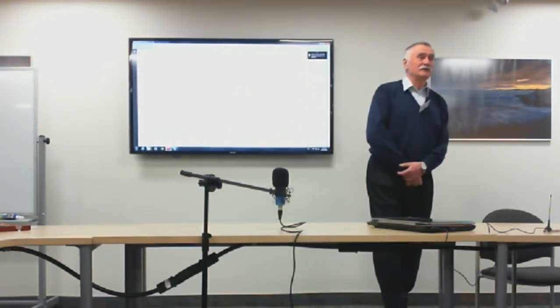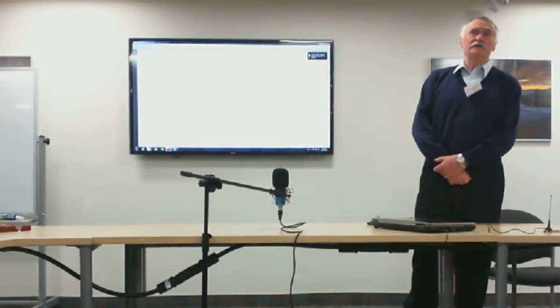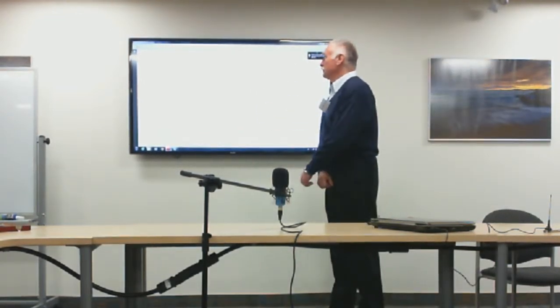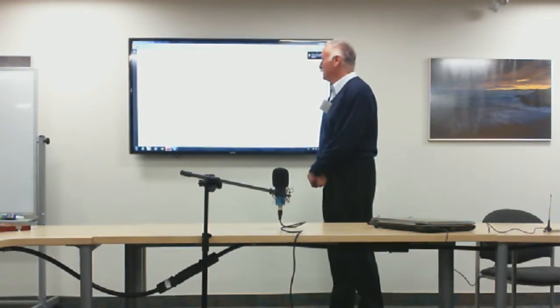Imagine 1 microvolt squared divided by 50 ohms, or even a top ham radio with a sensitivity of 0.2 microvolt, 0.2 times 10 to the minus 6 squared divided by 50. We are talking about a fraction of a picowatt. So the receiver must be very sensitive.